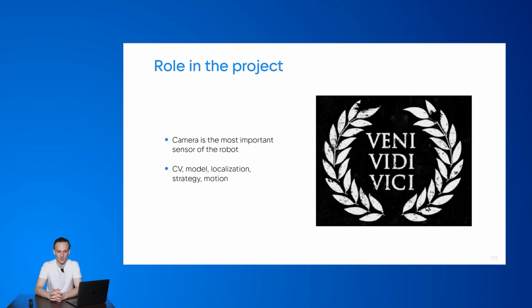In the last part of the pipeline, in motion, there are several levels of control that are implemented one on top of the other in a way that allows the robot to move its limbs in space properly. Our robots have 20 controllable degrees of freedom, so they're kind of complex, mechanically speaking. It means that the dimensionality of the output vector is 20. So the robot has an input, as we have said previously, of several million numbers, and its output is the positions of the servo motors.